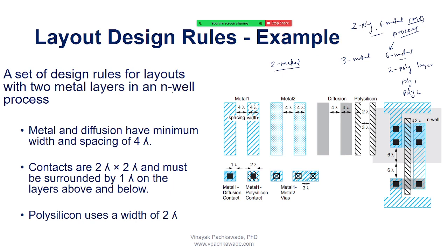So see now, I am having an N-well process. Okay, so it means I have a P substrate and I have an N-well process. So already I have an N-well built into that process. I don't need to specially fabricate an N-well using that technology. Try to understand the meaning of this sentence.